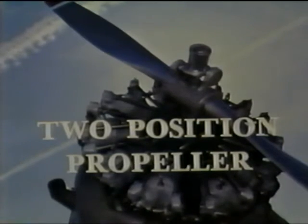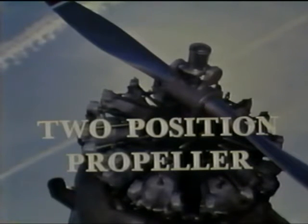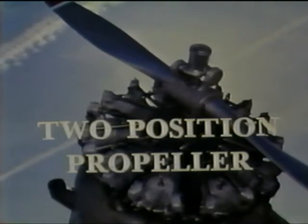A two-position propeller system is designed so that the pilot can select one of two blade angles in flight. This allows the pilot to select a low blade angle for takeoff and climb and a high blade angle for cruise.